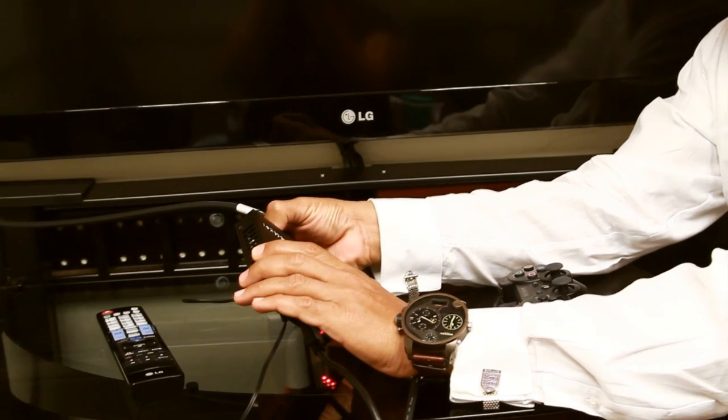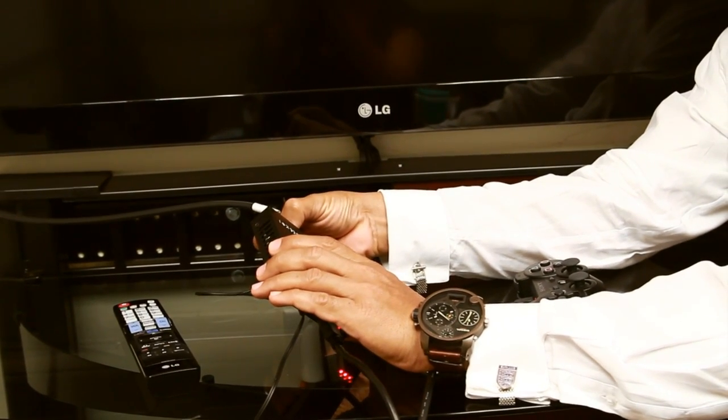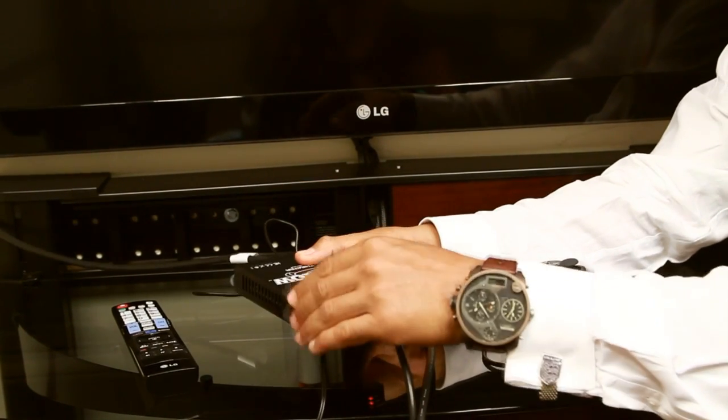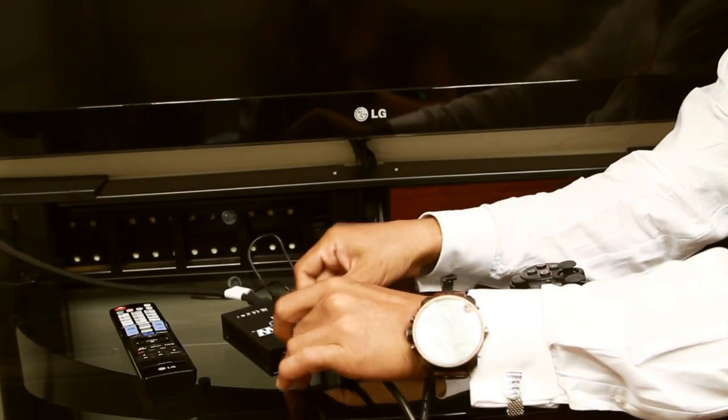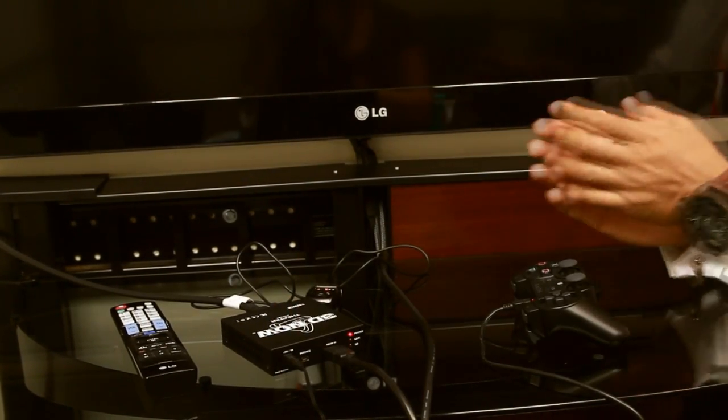And most often what you'll find is that televisions particularly aren't true 120 hertz, and they will have a value of 60 hertz on an input level. So let's see if I'm correct, and this really is a 60 hertz television. I'm taking the dip switch number 1 and pushing it down, recycling the power, and I'll see where I go now.